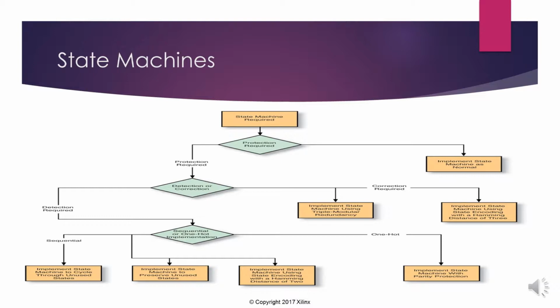We can map in all of the unused states, and then after power on reset, we can cycle through each of the unused states from one to the next until we get to the idle state, such that if we go into an unmapped state again, we will just come back into the idle state eventually after transitioning however many unused states there are.